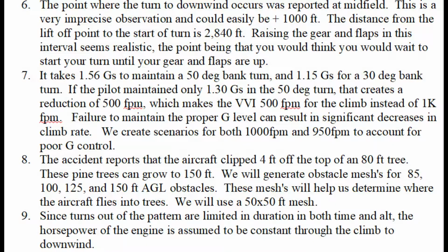The point where the turn to downwind occurs was reported at midfield. This is a very imprecise observation and could easily be plus 1,000 feet. The distance from the liftoff point to the start of turn is 2,840 feet. Raising the gear and flaps in this interval seems realistic, the point being that you would think he would wait to start his turn until his gear and flaps were up.